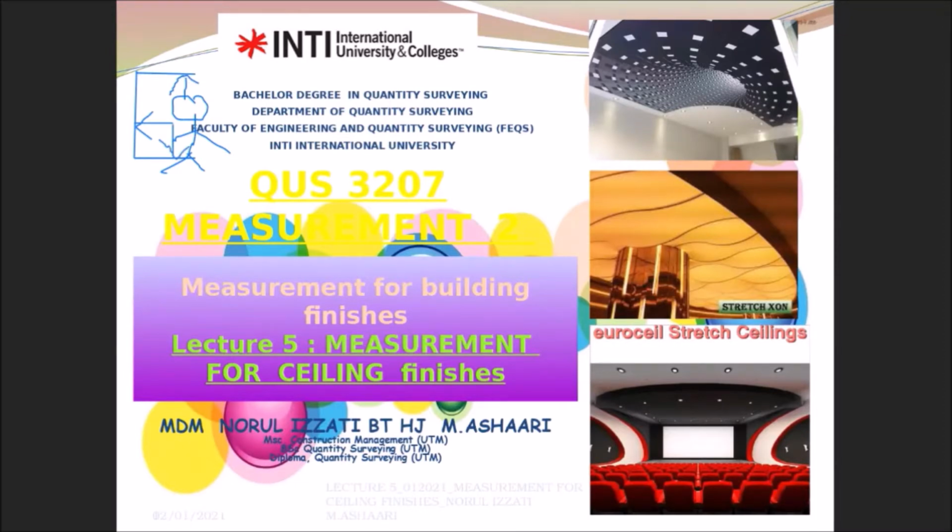So if I ask you the question, let's measure the building finishes, in your mind, you must have this C interpretation. You must have this C idea where you have to measure ceiling, wall, and floor. If I give you the specific task, okay, today let's measure for the ceiling. So you can see that this is actually part of the building finishes. Okay, staircase finishes is measured under staircase element, but ceiling, floor, and wall will be measured under building finishes.